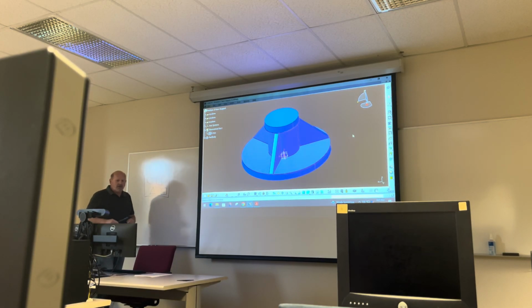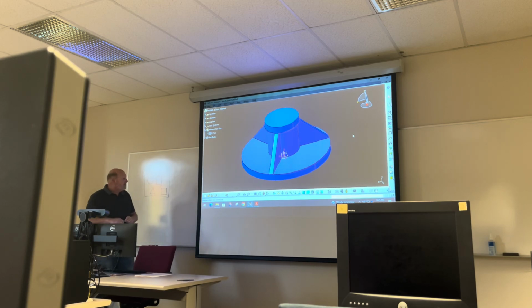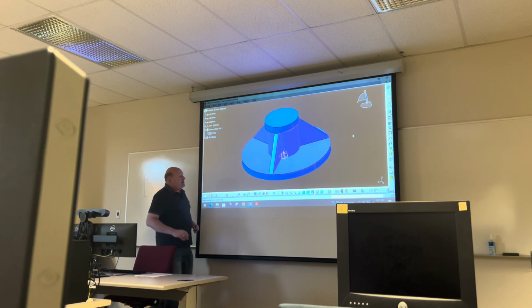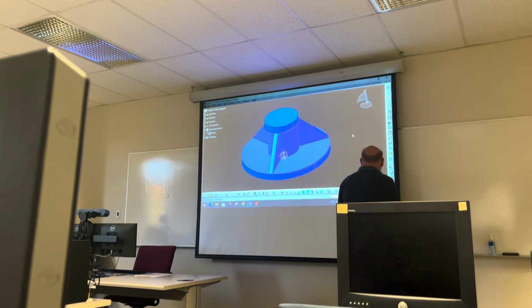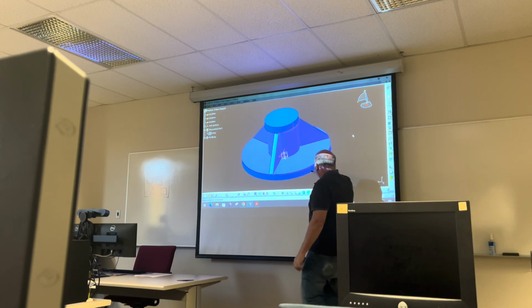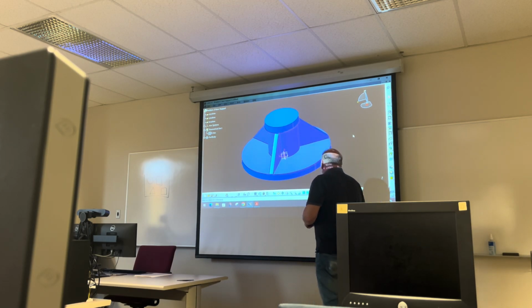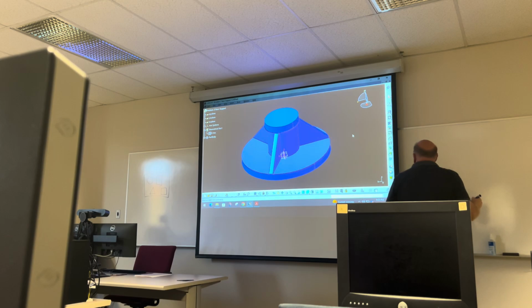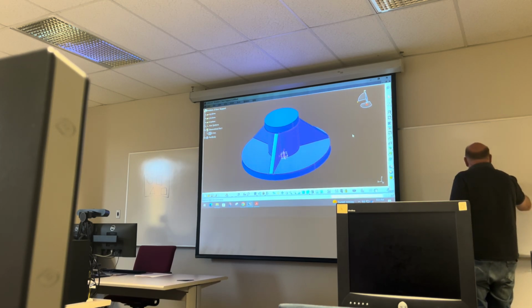That's correct, and I'll show you how easy this thing fillets when you do that. Because what a lot of people don't know is these intersections right here: if you build this as a cylinder, and this one as a cylinder, and you try to put these ribs in there, the issue is if you go to build that rib in the side view, it's going to look like this, right?